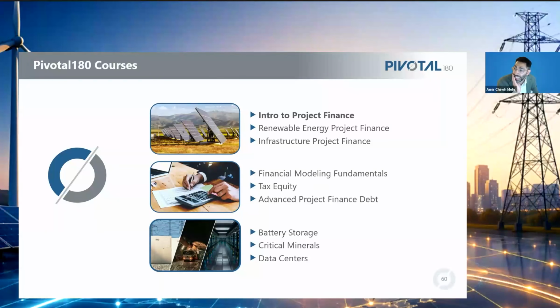Now, an excellent question is, how quickly can each additional plant be turned online if demand increases and our marginal plants are able to immediately meet this demand? The answer is yes and no. Some plants can be turned online almost instantaneously, and that might be why they exist. Like peaker plants, like I said, in some cases only operate a few hours a year, and the service they're providing is exactly that. They can turn on instantly.